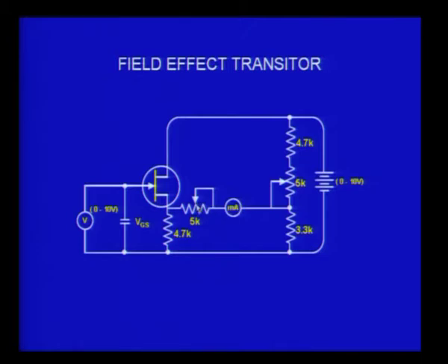You can adjust the 0 so that the current in this wing is adjusted to make it 0, and this is also used for adjusting the balance of the bridge. And now you apply any external voltage for whatever basic thing that you have, you adjust the 2 potentiometers and make it 0, and then you apply external voltage here.